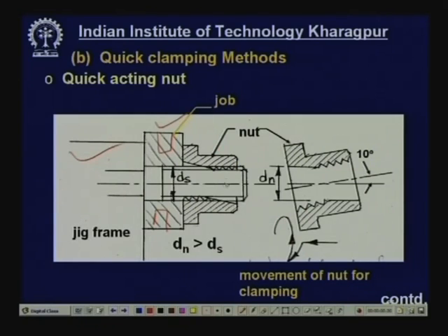There is a plug which is fitted into this one semi permanently, and then this blank is fitted here on this bearing surface. Then this nut has to be used. This nut is peculiar. It has threads, but up to a certain layer the thread is continuous, while this part and this part are machined out. A hole has been machined at an inclined angle, say 10 degrees, and threads from here and here have been removed. So, now this is how it will act.